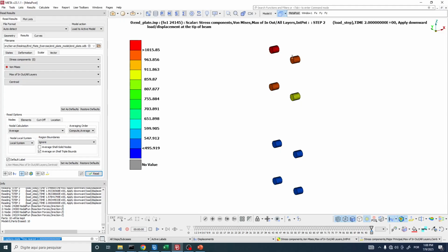It's like the representation of the bolt breaking in this case. But we would have to increase more the displacement. If you'd like to, you can try this. Okay, instead of applying 200, you can try to apply 250 to see these bolts losing stiffness. Okay, this is a good exercise.